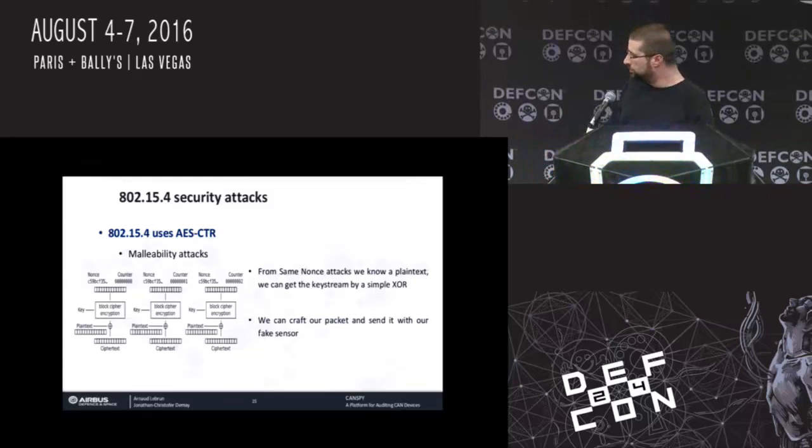The reason we were able to do so is because the supplier made four big mistakes that are very common. First, let me say that the usual way to work on that encryption aspect is to find a JTAG, a BDM, or something to extract the firmware, and from that firmware to extract the key. But since we were not able to do that, we had to work at the encryption level.